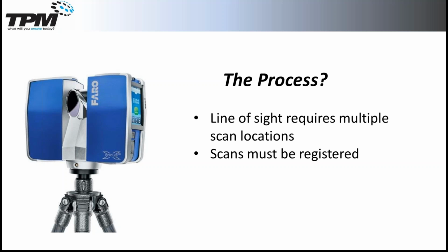All right. The process of taking multiple scans and relating them to each other is called registration. The hardware is an amazing measurement device, but there's one thing that it doesn't do, and it doesn't really know where it is. When it takes the scan, everything is going to be related to the position of the scanner. So that's your origin, and from there it's just measurements. So we have to use software to tie all of these different scans together and build the complete picture of our area of interest.